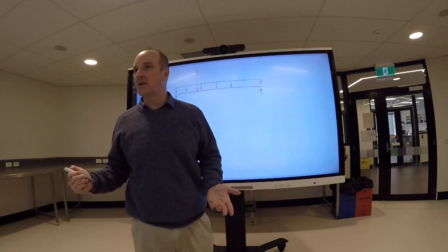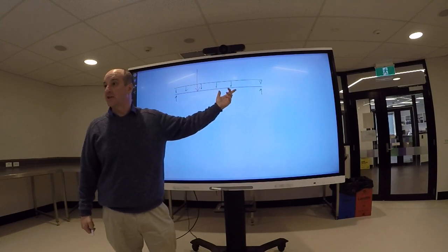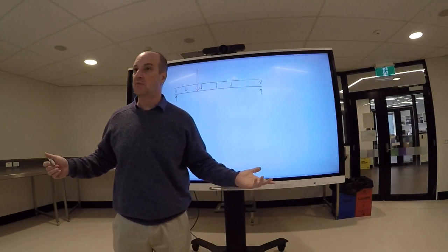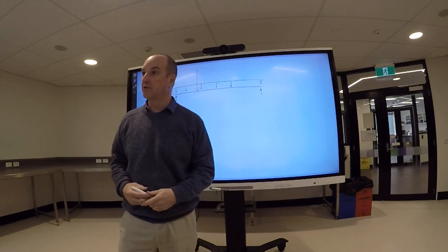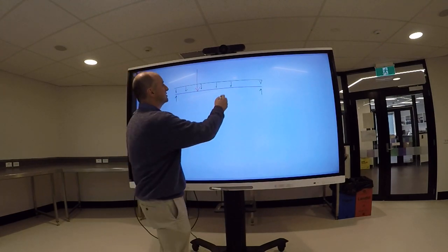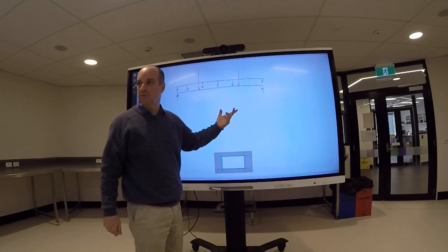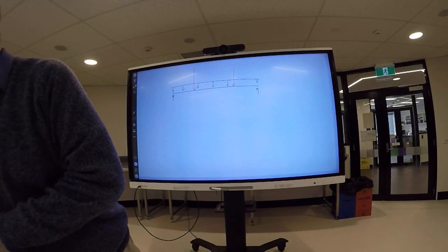You have to consider the different load cases, and you'll end up with basically different actions, all right? Where we end up is an envelope of actions on something, and then we have to make sure we design the capacity to withstand that envelope. So it might be fine with the load there, but if the load goes there and it collapses, you haven't designed it properly, all right? How's that going so far?